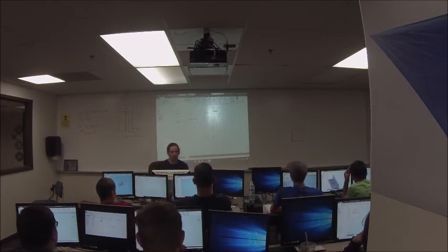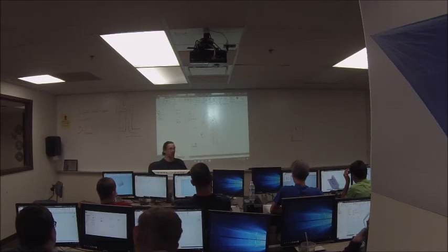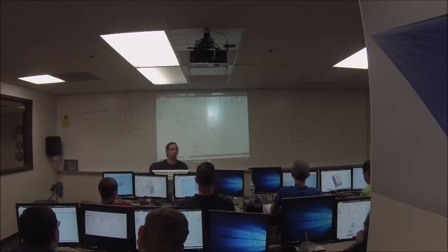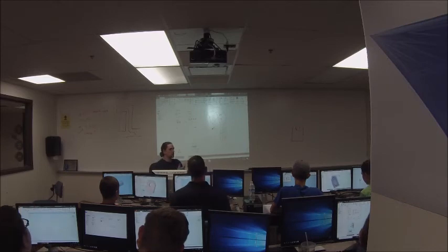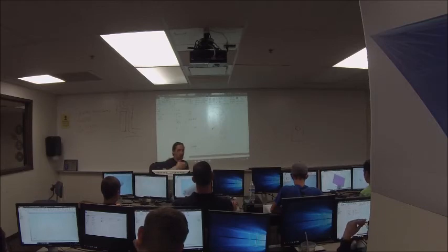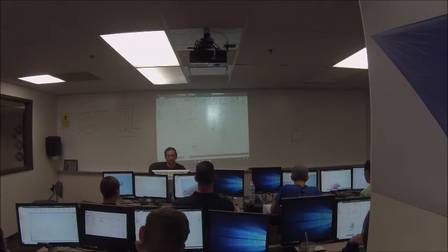So if I want to just extrude this region, I click on it, and all of a sudden, hey look, there's my 3D preview. If I want to extrude both of those, I can click on the inside one too, and it'll add it. You're basically keeping track of a list behind the scenes of what regions you want to extrude. Let's say I clicked on one by accident. Ah, crap. I didn't want to extrude that middle part. I wanted that to be a hole.